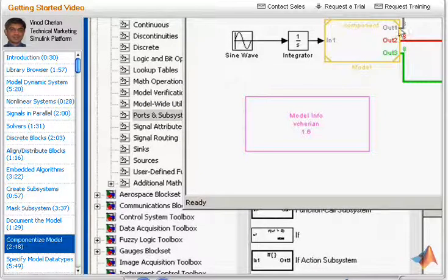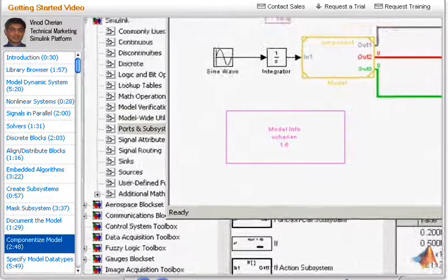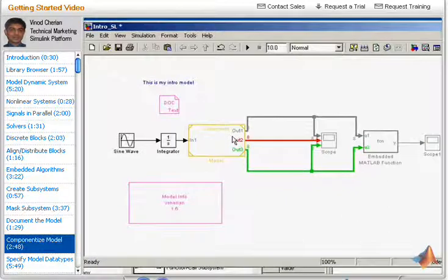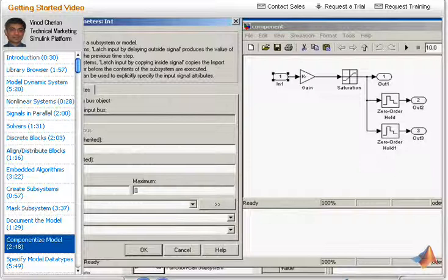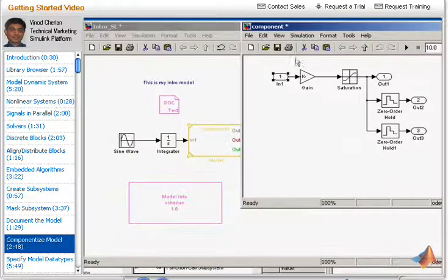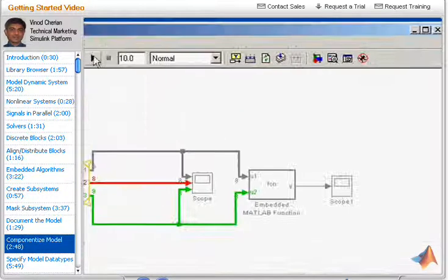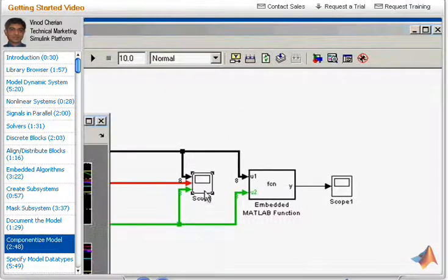As you can see, it aligns from a continuous time to sample time. And let's let this happen. If you double click on this model, you can see that there are no continuous parts in this model, and everything in this component can be run in discrete time. So what I'm going to do is force it to use a continuous sample time for the default input. I'm going to save this now, and I'm going to simulate this model. Let's look at the outputs, and this is exactly what the original system had as outputs.